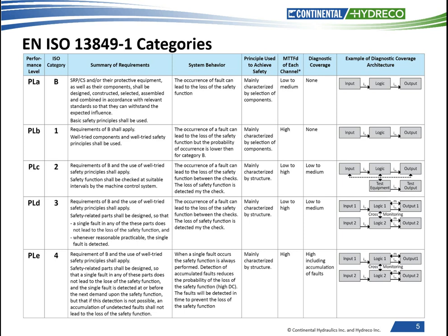With redundant systems, one channel or one valve can fail without losing the ability to stop the machinery because of the redundant valve circuit. Example, if one valve or monitored switch in a dual monitoring kit fails, the PLC can still shut down the second valve that will block the supply and bleed down the output as designed.